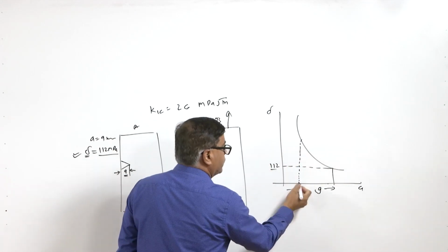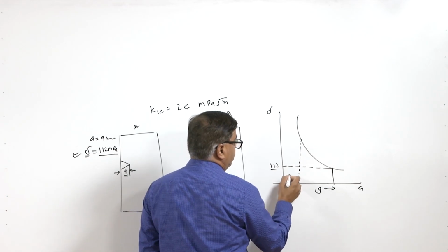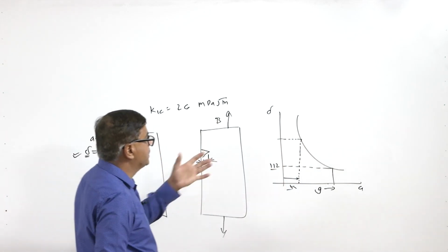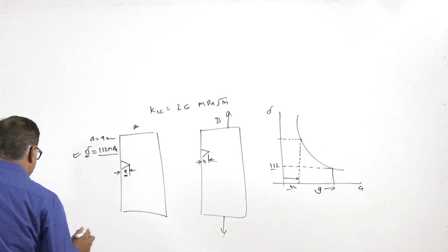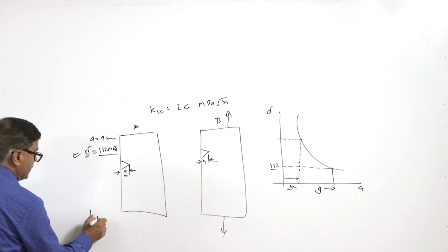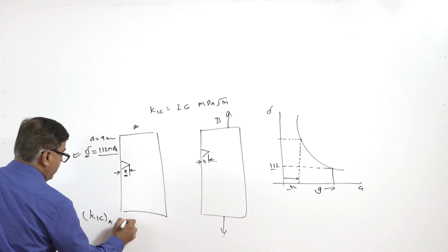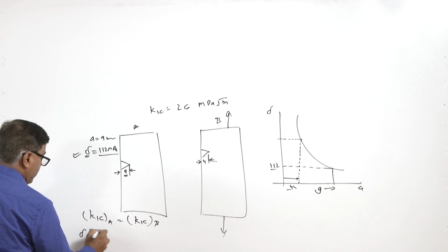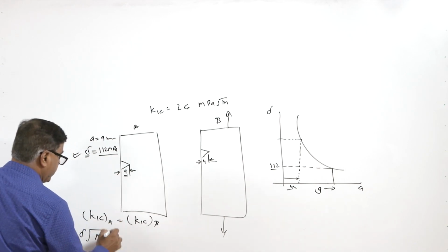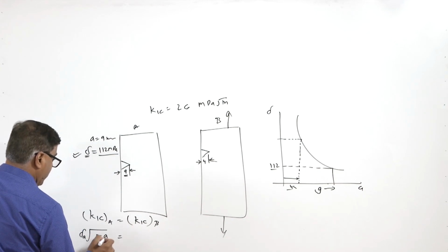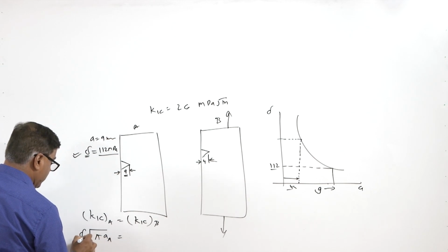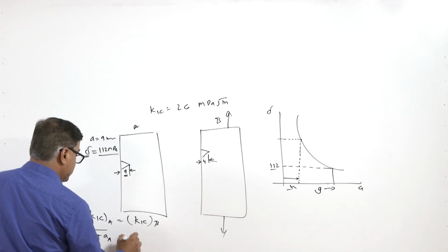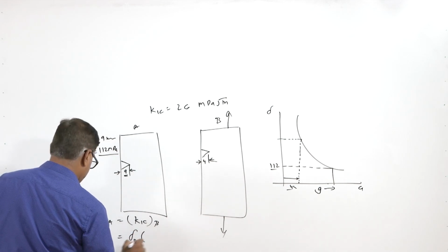So, for the smaller size of the crack, say of 4 mm, the applied stress will be on the higher side. If it is required to determine how much size it can tolerate, we can determine that simply, since K1C for A is the same as K1C for B. So, we can write sigma under root pi a for the system A, so sigma A and a A, like this, for distinguishing case A and case B. Similarly, for the other metal, sigma B under root